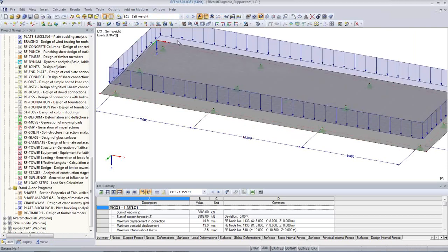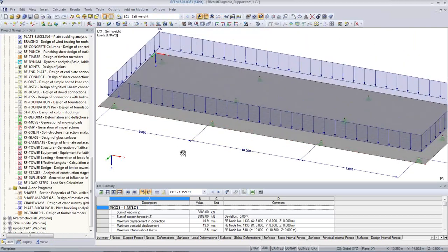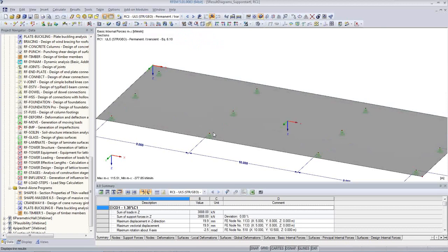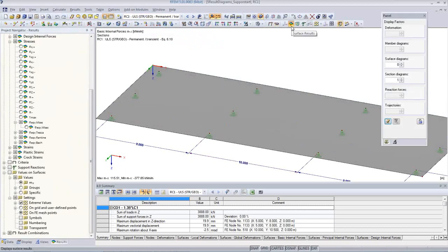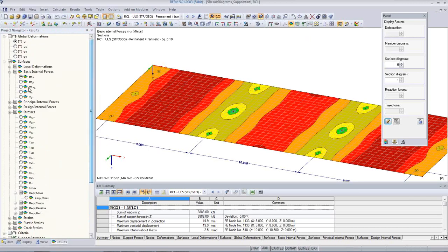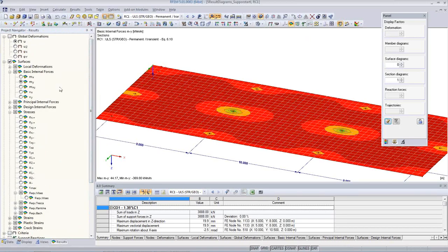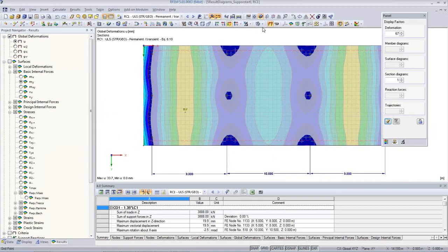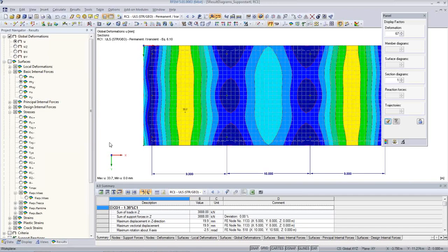Doesn't have to be many. It just needs to be showing the principal work with it. So there's self-weight and then there's a live load, and I have a few combinations, this time linear. Ultimate limit state results are, for example, we can see here the mx value, my value, and so on, or we can take a look at the deformations. Okay, what I like to point out is a typical problem, which are singularities.